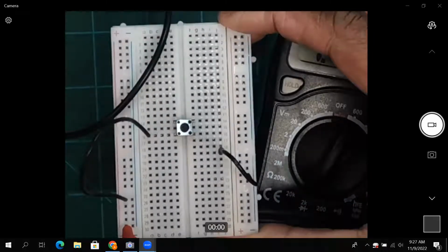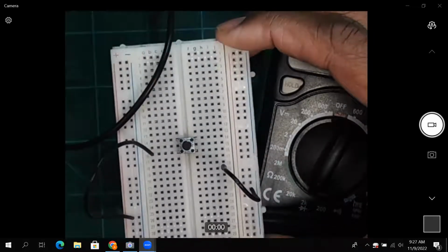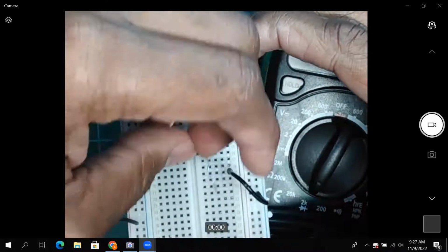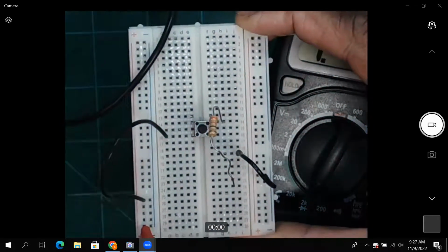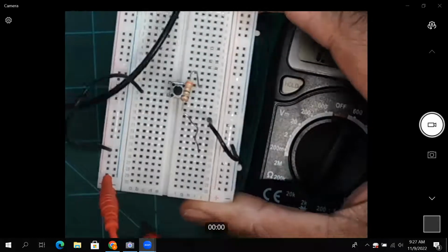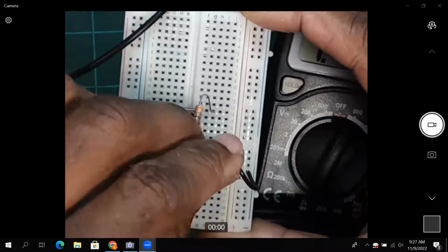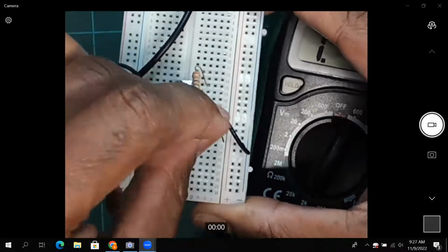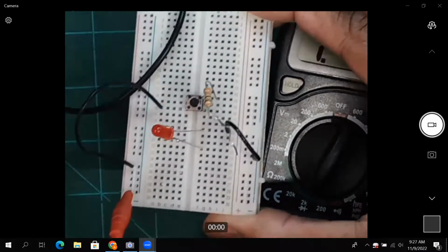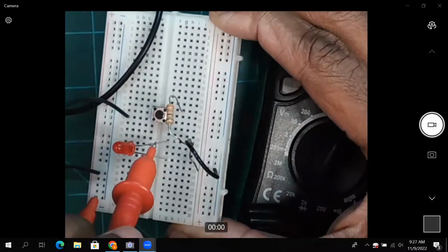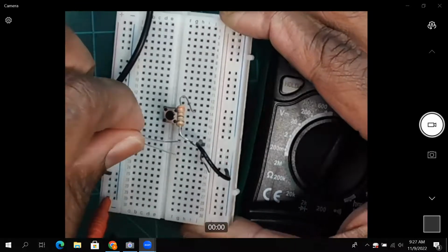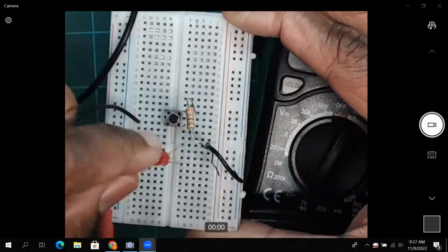So what I'm going to do is put my resistor on row 14. Okay, put it on row 14, and I'm going to have my LED. I bent it a little bit, so bend it this way. There we go. So I have my positive, longer leg right here, and my shorter end of my LED leg, let me just pick a row, on row 22.